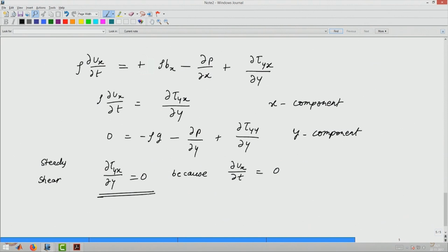So, this is the final governing equation for steady shear flow, and based on linear momentum balance, we arrive at the conclusion that the stress in the fluid is constant. We cannot say at this point what the values of the other components are, and how we measure them clearly depends on pressure. For example, depending on how pressure varies, we can then look at tau y y.